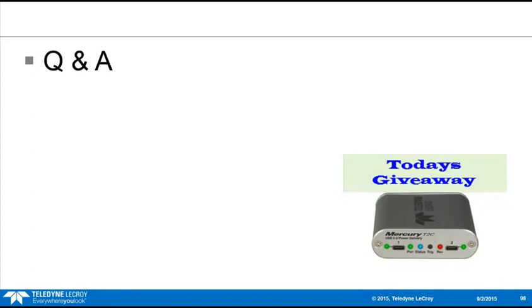Do we require PD for data role switch? Is PD required for a data role switch? That's a good question. Power delivery is optional. So that piece, I believe, is not required to do a data role switch. So you could implement a Type-C. You'd still have to have the Type-C logic for doing Type-C communication. But I think theoretically it would be possible to make a data role only switching mode and skip all the PD stuff.